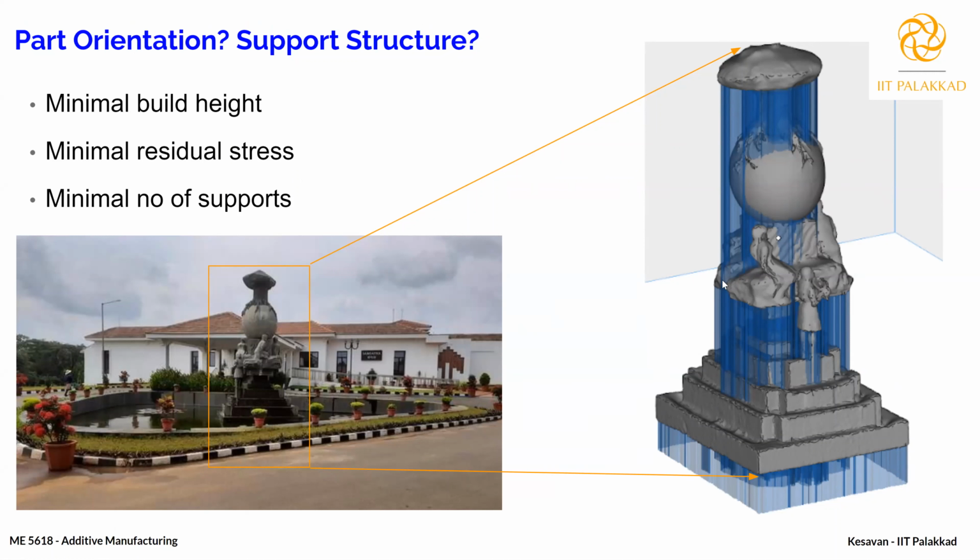So now the challenge here is it has so many angles, so many diameters, so many overhangings. So you need to think which orientation is the right orientation to keep this component for a better quality of print. Okay. And also you are avoiding support structures.